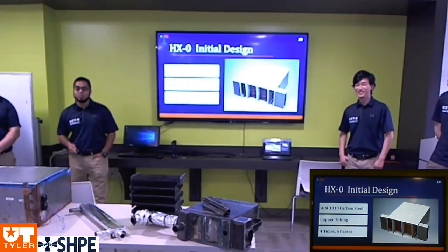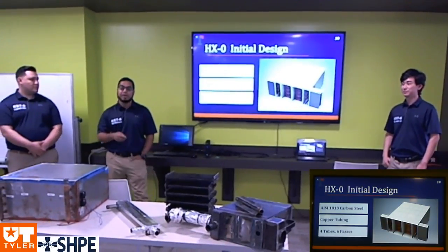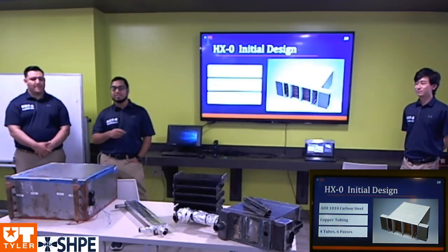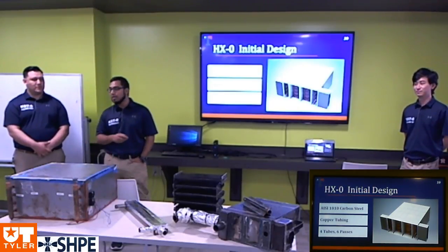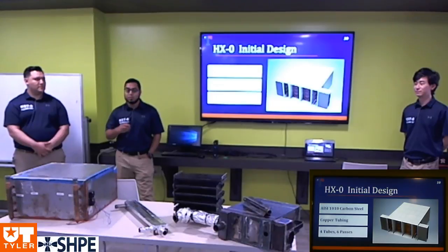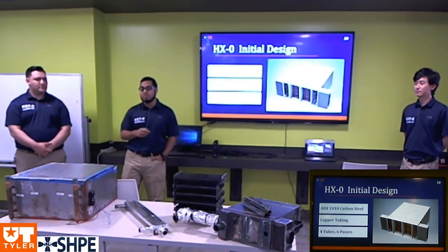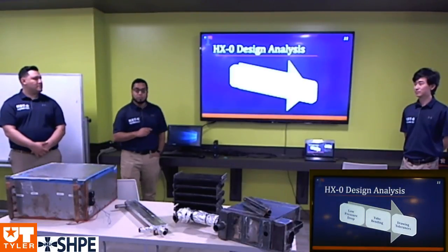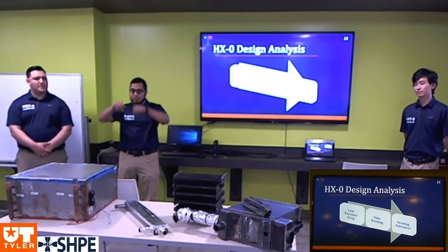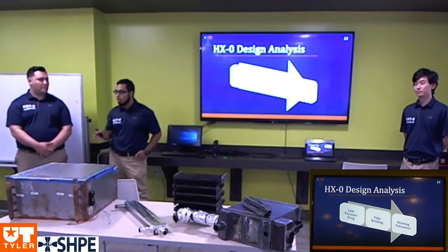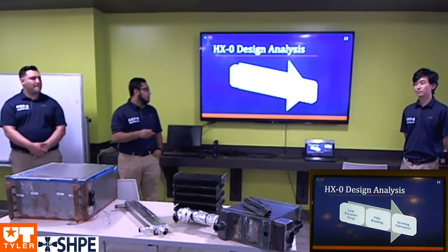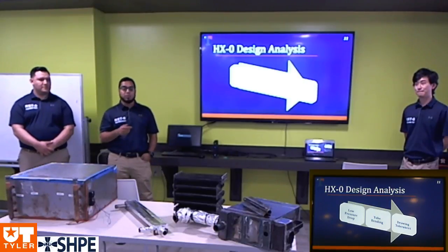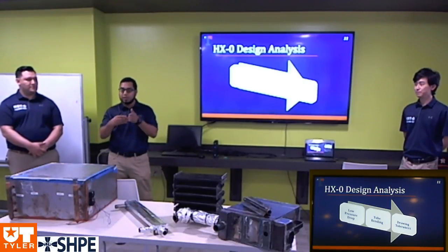It had 4 tubes making 6 bends and multiple baffles. The shell material was made out of 1010 carbon steel, and the tube was bent using soft copper piping. We learned a great deal from both the fabrication and the testing. What we learned was that we had a low pressure drop, that we wanted to get rid of the tube bending as it was really hard to work around during fabrication, and most importantly, we had to be more lenient with our drawing tolerances. So when we did fabricate the pieces, they would fit better.